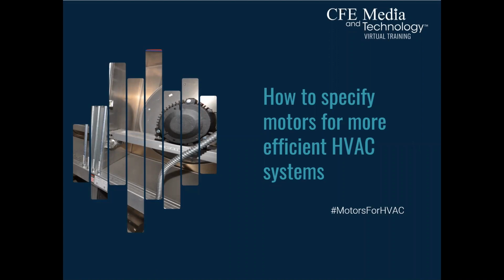This whole idea of taking out the VF drive and putting in a standard motor starter is counterintuitive to the standard practice today, because our goal is always to reduce first cost and reduce operating cost. Instead of being able to reduce operating cost by the addition of the VF drive, we're proposing that we can reduce the first cost by not having a VF drive at all, and we can also reduce operating cost by having a fixed speed motor.